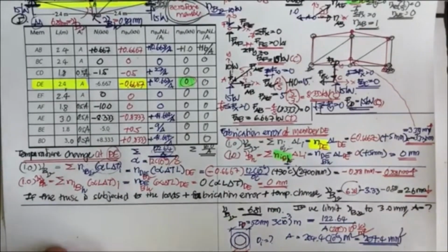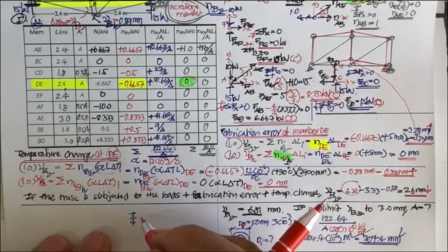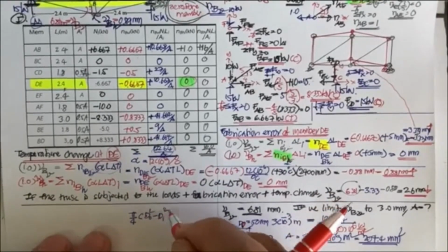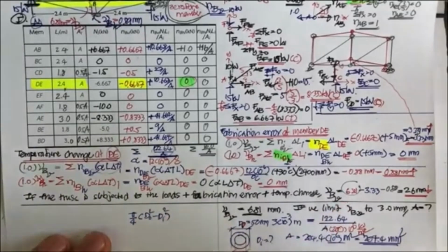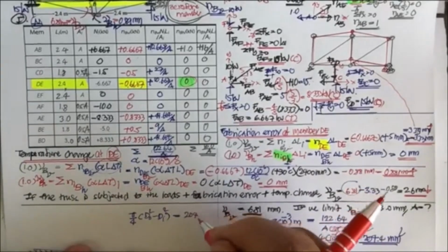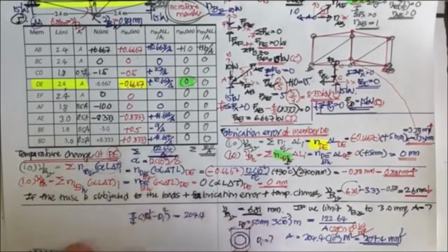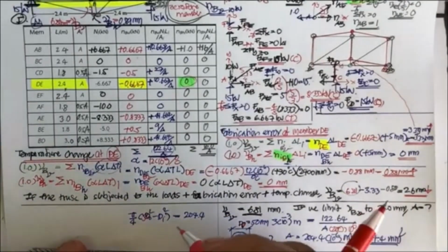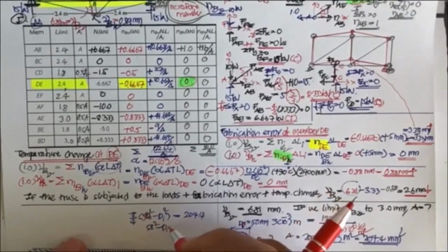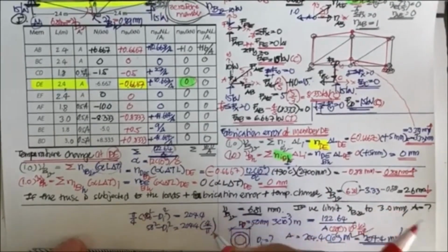Now you have the area of pi over 4 times D sub O square minus D sub I square, which is going to be your area of 204.4, and D sub O is 50 square. So you will have 50 square minus D sub I square equal to 204.4 times 4 over pi.